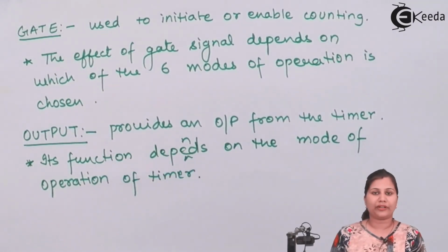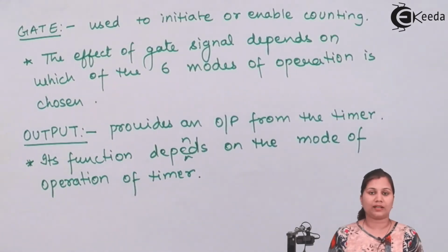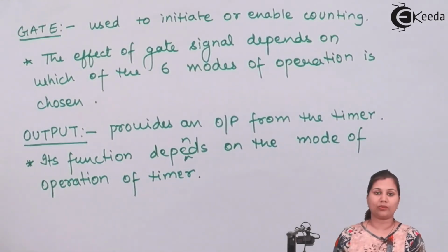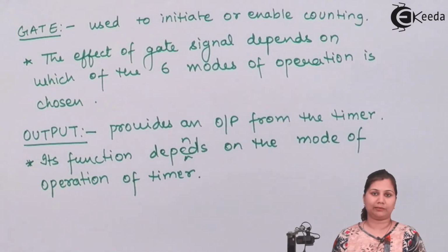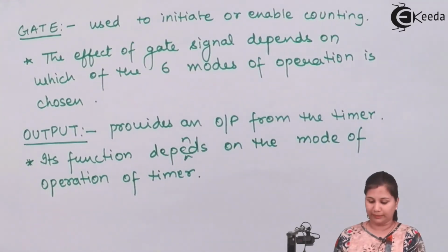In the 8253 we have 3 16-bit counters, which are down counters. That means they are initialized with a count, and then they decrement the count until its value becomes 0. Now to understand how the timers work, let us see the internal structure of the timers.